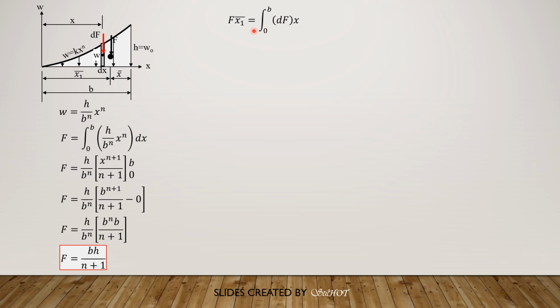So by Varignon's theorem, F times bar x1 equals integral from 0 to b of, this is the moment of its component, differential force times x.